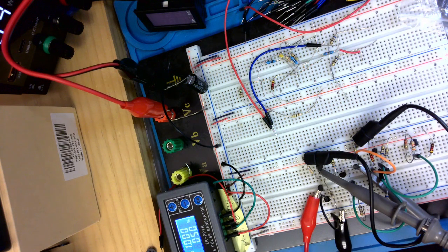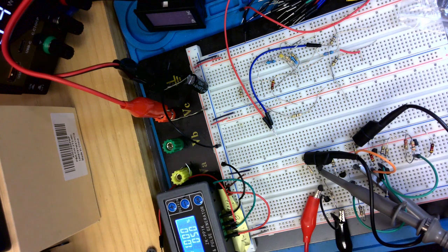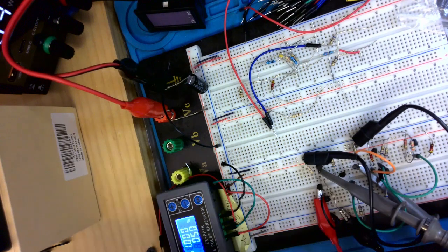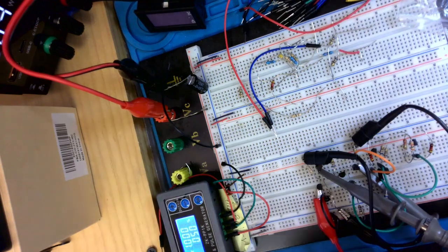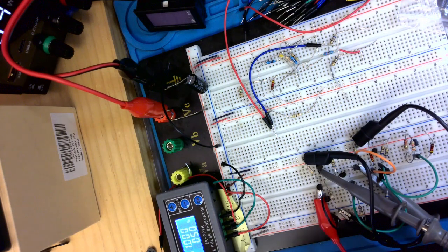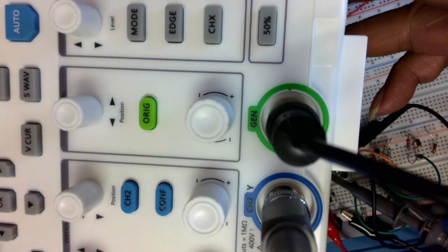So now noise seems to come from this guy, and I removed this and used the pulse generator from this oscilloscope. This oscilloscope can generate the pulse, and the pulse is AC, not DC, so it skews the waveform quite a lot.